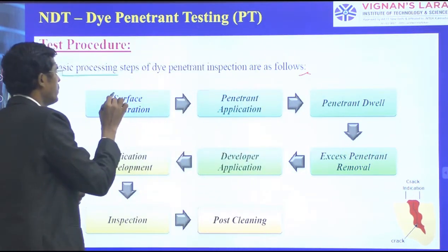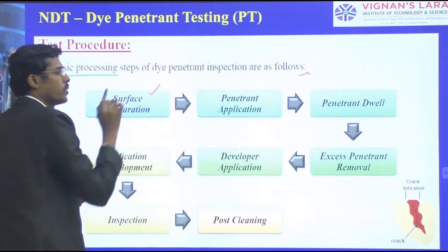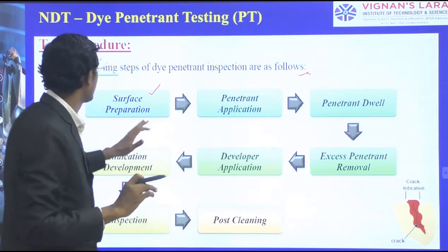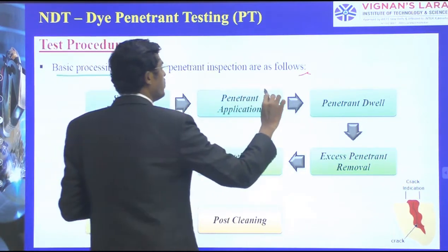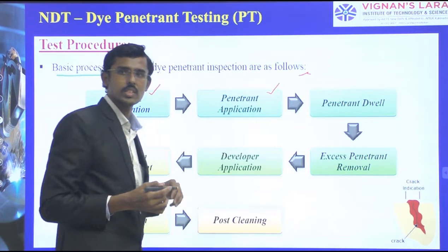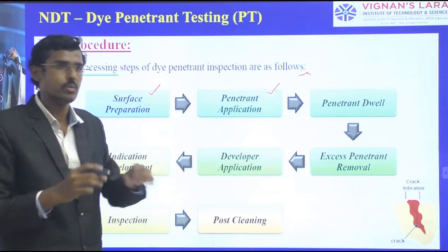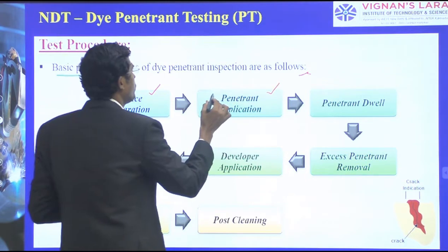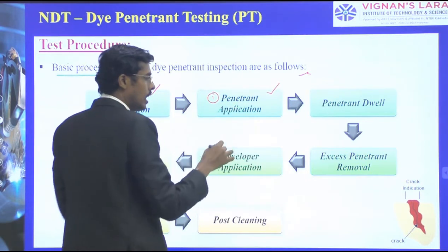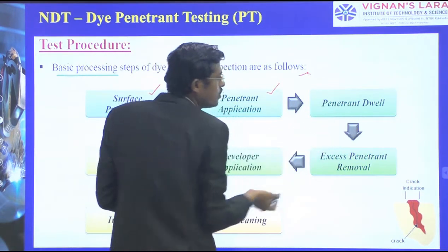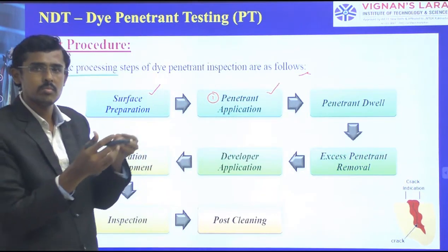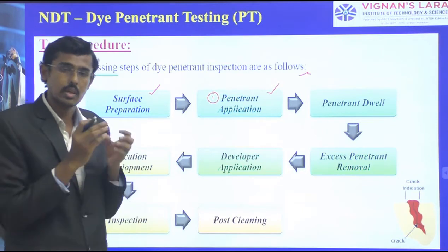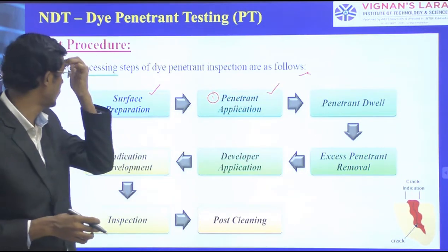First, surface preparation is to be done, such as a cleaning treatment. Second, we do the penetrant application. Here we are talking about two important technical terms. After the penetrant application comes the penetrant dwell time. We should give some time for the penetrant to get into the cracks. That's why we are giving a penetrant dwell time.